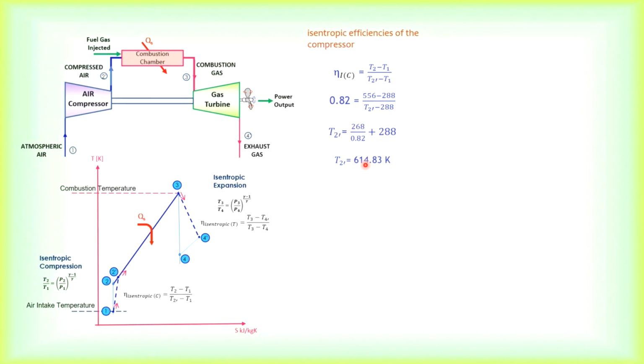So on this gas turbine unit cycle, the first thing we need to do is find out all the relevant temperatures. If you are using enthalpy, then you will have to find out all the enthalpies of each of these points. But for the gas side, you won't know what type of gas you are using, so you cannot use a gas table unless they have specified what the exhaust gas is.